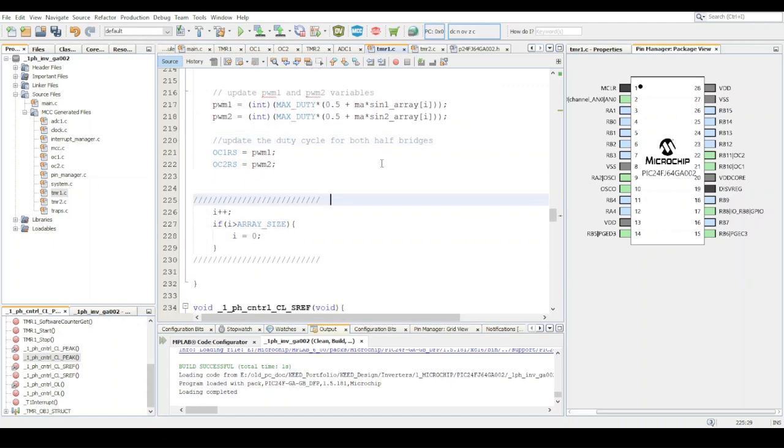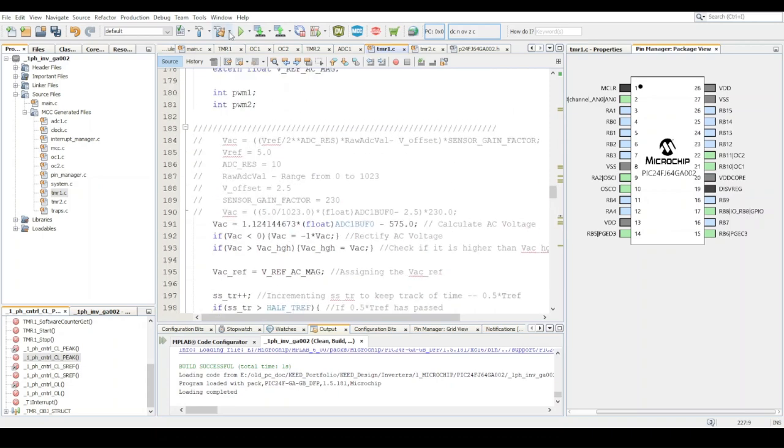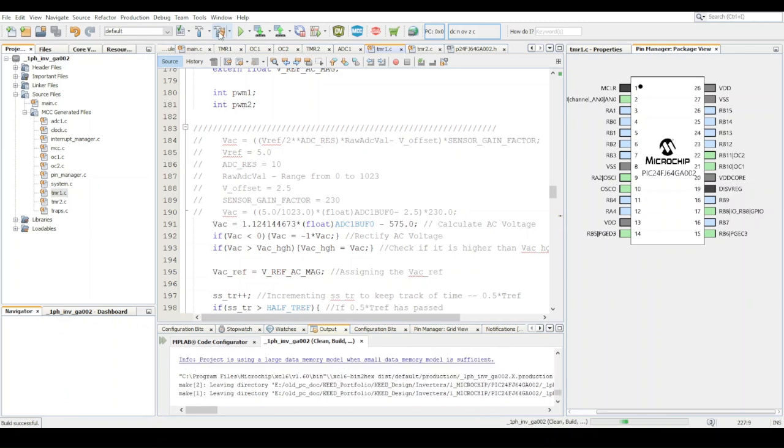And then lastly, you want to make sure that you keep track of the array element for the SPWM. Right, and obviously here restart the array if overflow occurs. And of course, overflow will occur once we get to the end of the array size, which in this case is 100. So we can start the sinusoid again. All right, so that's about it. So let me just run that. Okay.